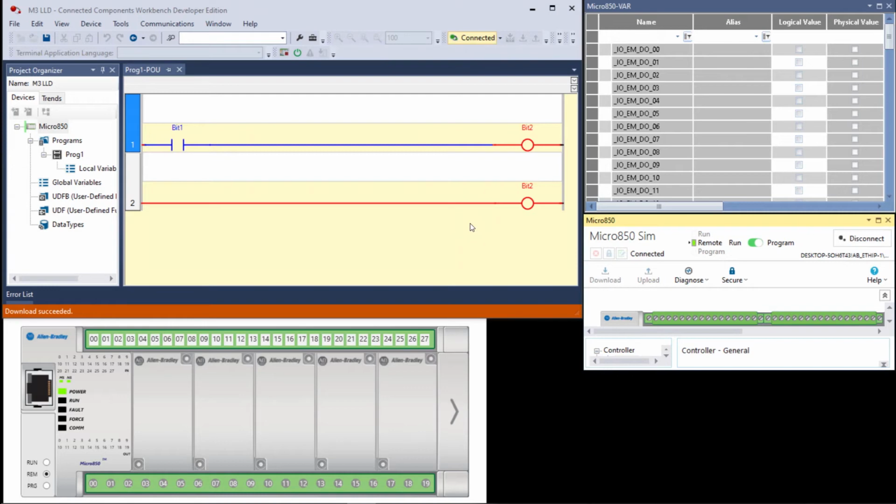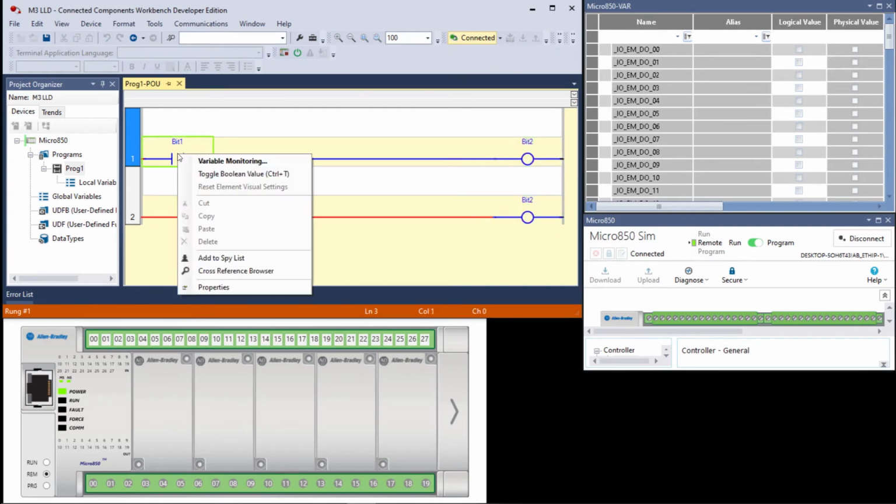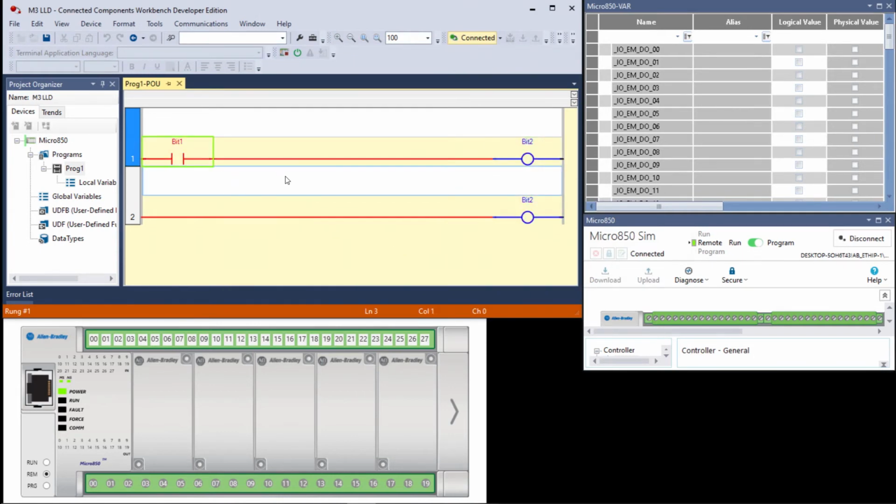Then we had you toggle bit 2 off in the program mode. Toggle bit 2 off. Okay. And then toggle bit 1. The question in the manual was, looking at this, what mode would you say the controller was in? Now you can look over and see it's in the program mode. But if all that you could see was this, what conclusion would you draw? Both these rungs are true, but in both cases it's showing bit 2 is off.